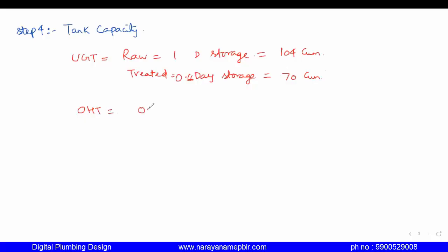Next is your overhead tank. Overhead tank is 0.33 day storage, which I'll calculate by subtracting this from the total, so 34 or 35 cubic meter I'll take. Is it clear? Yes, sir. So these are the tank storages for underground.